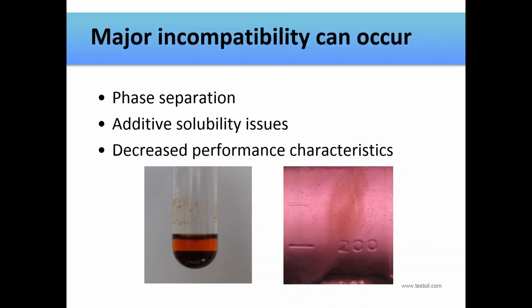The user should really be concerned with the 2 fluids' compatibility, even with the system seals and hoses and gaskets and other machine components, in order to prevent degradation or damage to the system components. And then we have the 2-phase fluid, which can really just impair the system from receiving appropriate lubrication and load-bearing properties at that point.